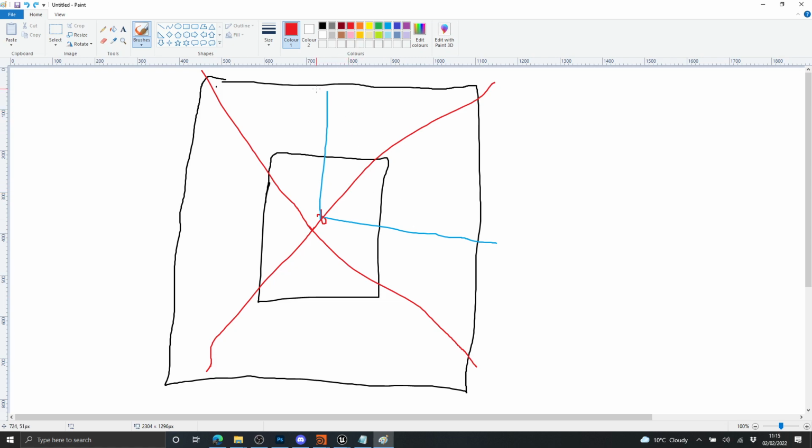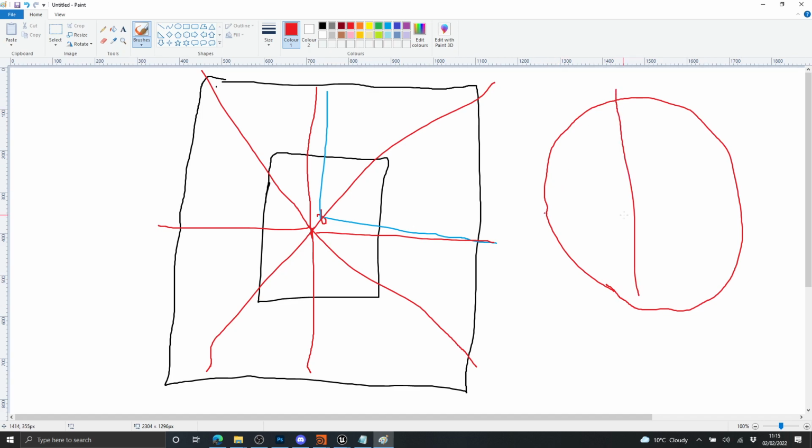And you can continue to push that even further, and you can divide that background terrain up into smaller and smaller slices. Just bear in mind that you will be introducing more draw calls if you do so. I think this is a good number of slices, kind of a pizza slice of the background terrain. So what's that? That's going to give us 1, 2, 3, 4, 5, 6, 7 or 8 slices.